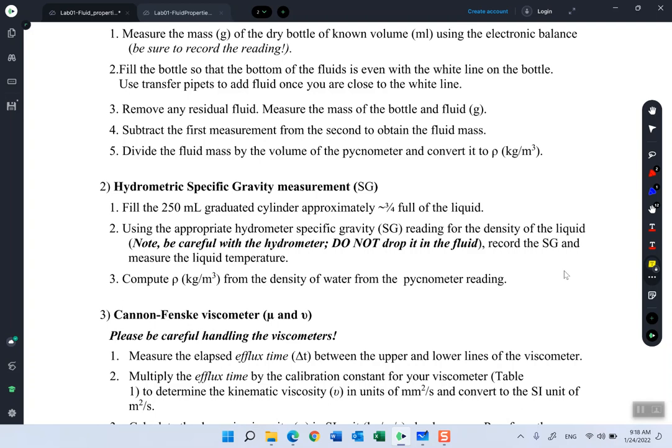The ruler says that at this point, the specific gravity is 0.7, and at this point, the specific gravity is 0.8. So we drop the hydrometer inside the cylinder, and it will have a certain location. What we are going to see is where the water surface lies, in which position.